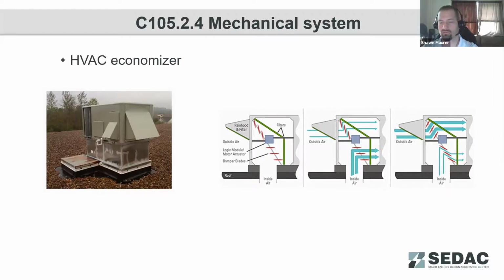When you're calling for minimal outside air, you want to make sure that those dampers are then not fully sealed so that you're getting that 20-30% minimum, whatever that ASHRAE minimum outdoor airflow rate is. So those are things that are going to be checked as part of that commissioning process and as part of the code compliance process. Something else that will be checked is that the high limit cutoffs are properly in place on these systems. Again, you don't want the economizer operating in a condition where it's actually adding to the energy load of the building. And that's what that high limit cutoff is looking for.